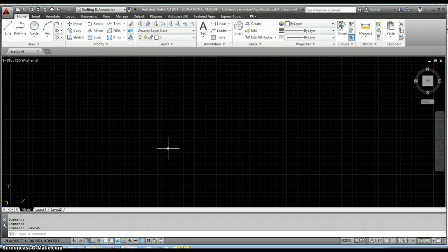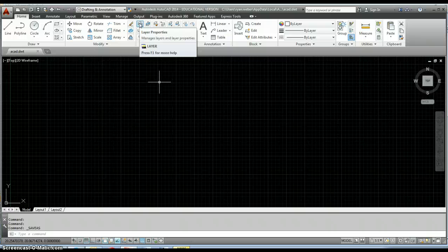Alright, now you'll want to go ahead and close out of this drawing and open a new drawing, and then check your layers. You'll go back into this Layer Properties Manager and make sure that your layers show up. The other thing that I want you to do to complete this portion of this assignment is go to your neighbor, and pull up the properties for your drawing template, and have them check that you created all of your layers correctly with the correct name, the correct color, the correct line type, correct line weight, and the correct plot setting.